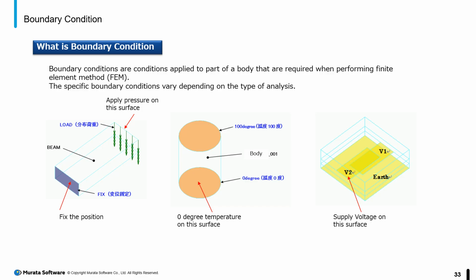For example, in stress analysis, you may apply loads to the face of the body or fix them in place. In thermal conduction analysis, you may fix the temperature of a surface or set heat dissipation conditions. In fluid analysis, you may specify the flow velocity at the inlet and outlet faces of the fluid.